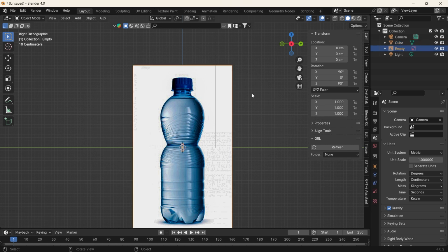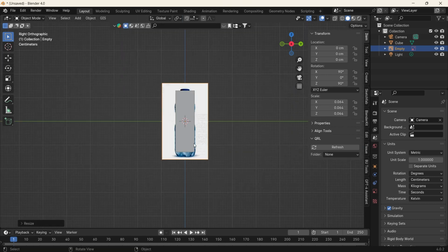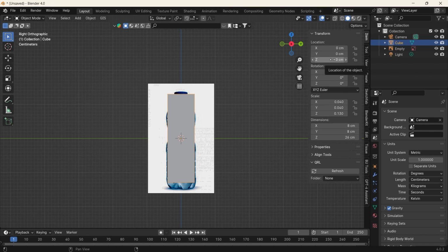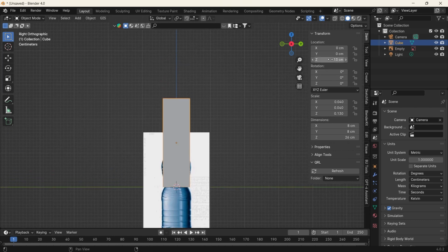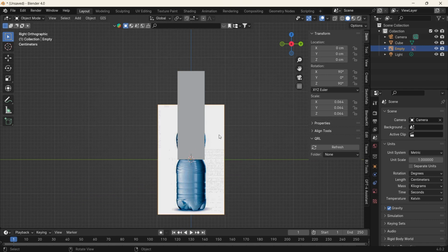So you can tell that this is a very huge image. But we're going to scale it up. Sorry, scale it down. Bring it down. And let me let the cube sit exactly on the grid plane. We normally do that by dividing the total height by 2, and then using that on your z-axis, you get it always to sit on the plane with the origin always in the middle.